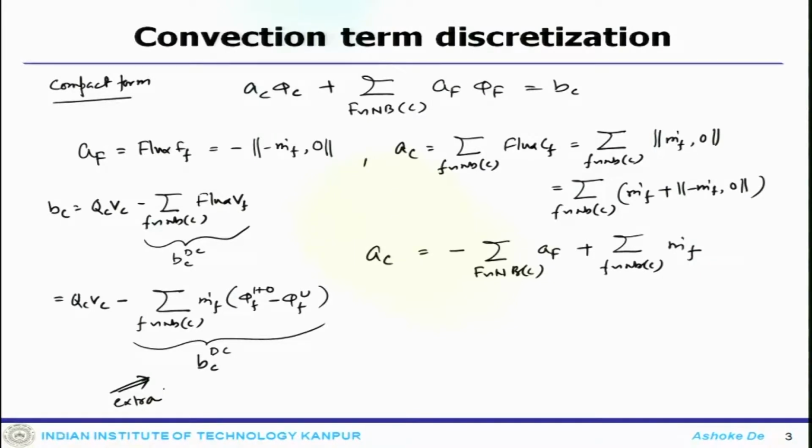On top of that, this deferred correction technique results in an equation for which the coefficient matrix is always diagonally dominant, since it is formed using some sort of an upwind scheme. So, the computing procedure is simple to implement. However, as the difference between the cell face values calculated with the upwind scheme and those calculated with the higher order scheme becomes larger, the convergence rate diminishes.